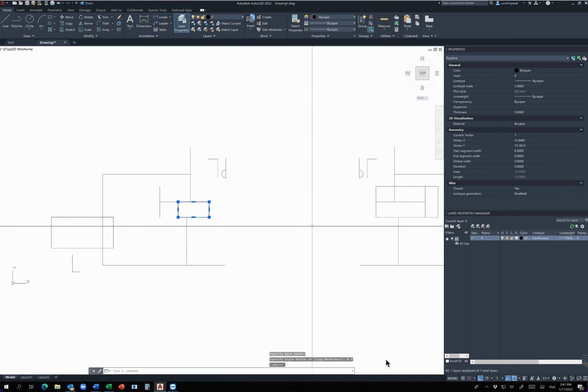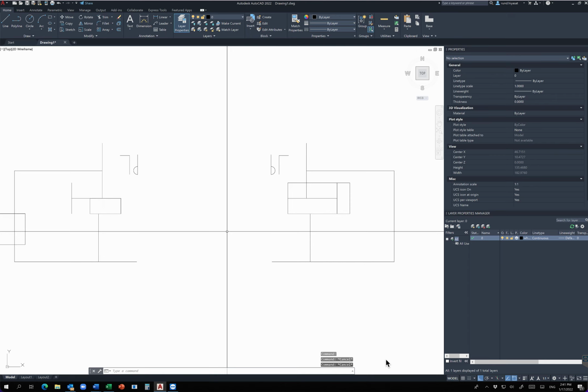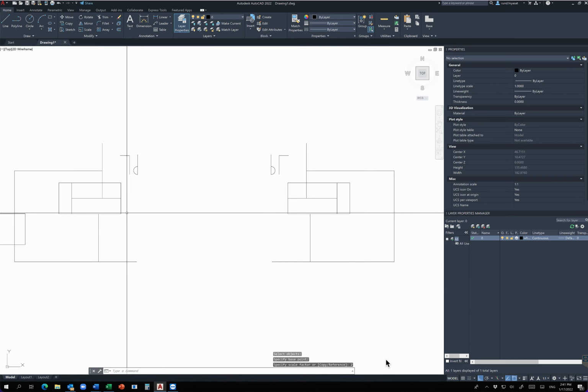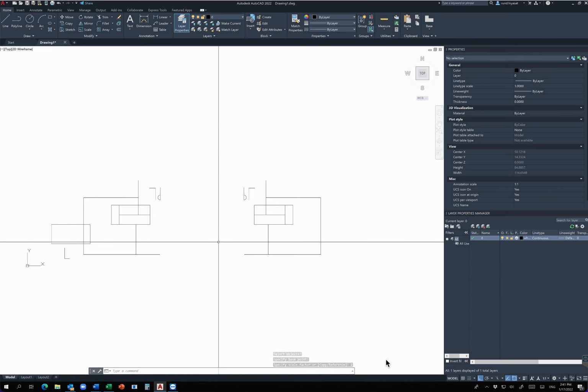or the rectangle. So if I want it to be twice as big again, then I'm going to escape everything, type SC again for scale, hit the enter button, and then place a short click on the object that I want to rescale. And then I'm going to right click. The base point is this one, and I want it to be twice as big to bring it back to its original size. So this is the scale button or the scale command.